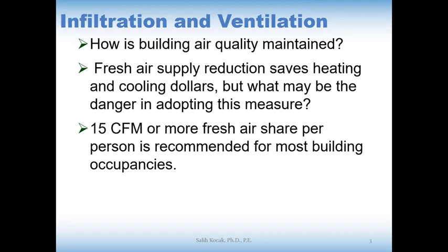And this number changes, and I have some information from the old years. There were hotels. In hotels this number goes all the way to 30 CFM for bedrooms plus 35 CFM for bathrooms. Okay, 30 for the bedrooms and 35 for the bathrooms in the hotels. And if you're going to places, it's not very common in the States, but there are still places in Europe where smoking is allowed.